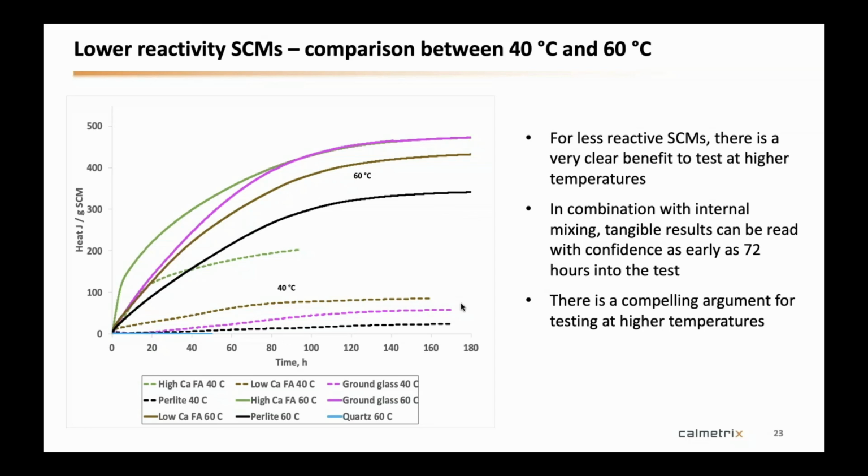Now the calorimeter is built to maintain the temperature at 40 degrees C. So the ambient can be 23 or something else. It's okay. The calorimeter will maintain the temperature very stable inside. Of course, like with every calorimeter and every type of apparatus like that, if your ambient temperature fluctuates, you'll see small fluctuations in your calorimeter too. So you have to keep it as stable as possible in your lab. But no, you don't have to do anything. The calorimeter is a curing chamber that handles its temperature on its own.